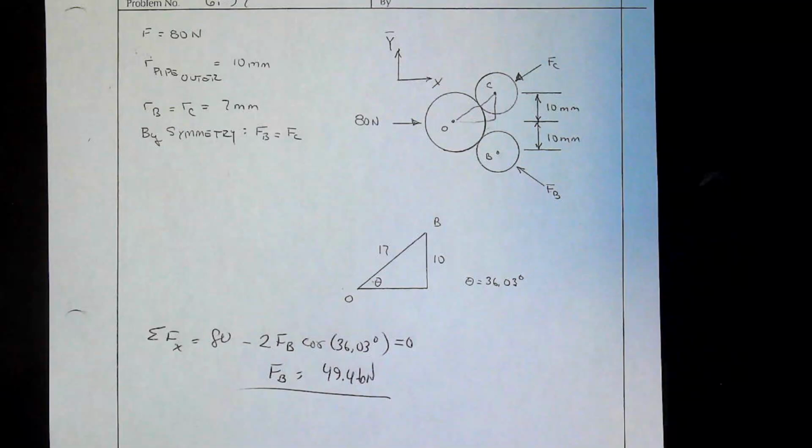Then you're left with this has got a leftward component, that's got a leftward component. That means this one's got to go to the right. So from the free body diagram, there's really no reason when we solve this problem that you should go, oops, I guessed wrong on the direction. It's apparent. Okay, so given this, knowing FAC, if we sum forces in the y, we get FAB. Then sum forces in the x, we get FAD. So you would have this.